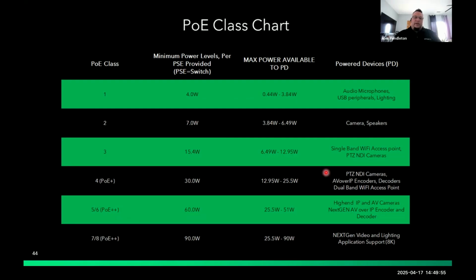You also see some in the PoE plus 30 watts, a lot of things in the 30 watts, and all of these types and all of these classes are backward compatible. So if it's a PoE device, it can totally work on a PoE plus or PoE plus plus port as well. And then you see the next gen video and lighting applications, 8K systems will all be in the PoE plus plus realm of power for sure.